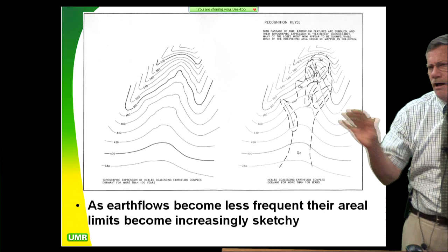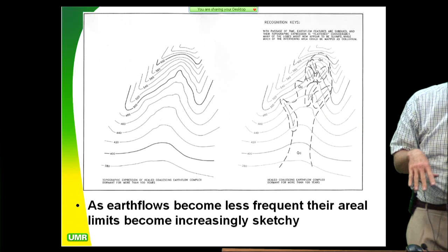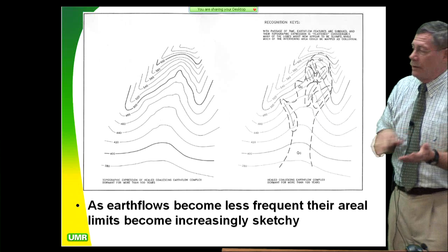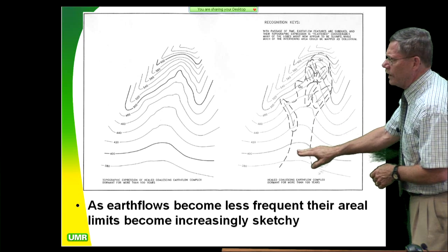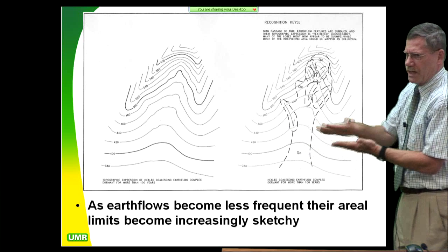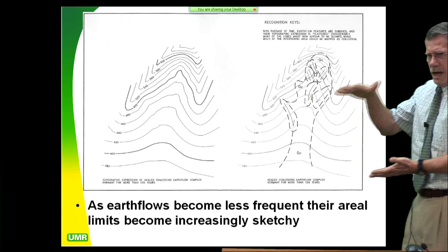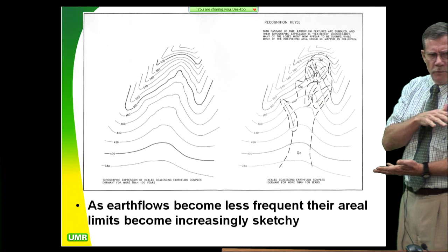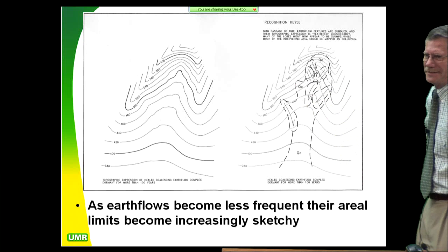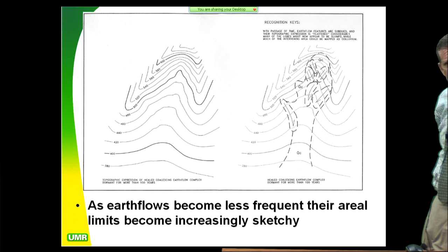And I used to get into all kinds of technical arguments about that. And one of the arguments was, well, we trenched it, Rogers, and you're wrong right here. We trenched it, and we don't see a slide plane. There's no defined slide plane. We just got this colluvium on top of a rotten grass layer. I just started laughing. How do you get colluvium on top of rotten grass? Only one way I know of. It's either dumped there by an ancient Indian dump truck, or it was a landslide that dumped it there.